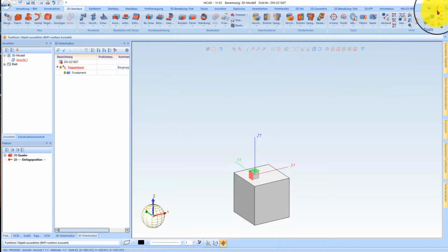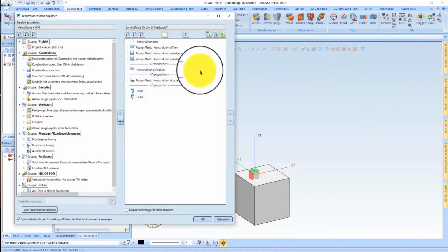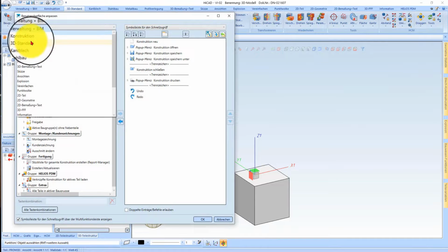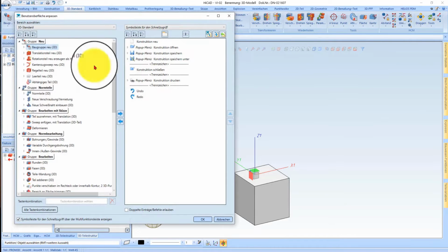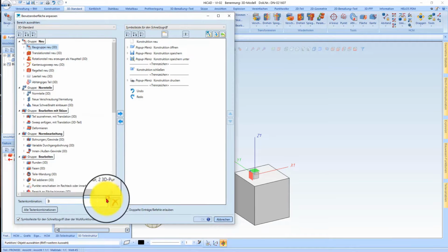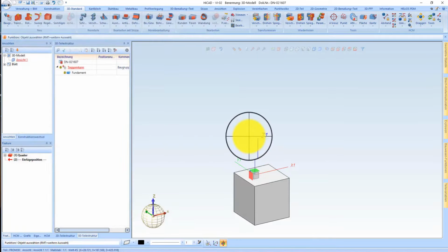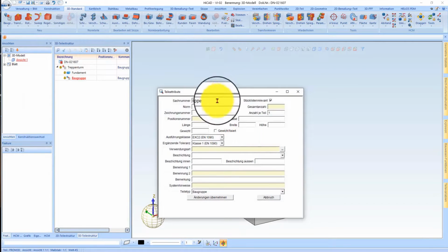What is also important, and what I always want to emphasize, is adjusting this so-called user interface. That means I can, for example, search through my commands here. For instance, I want to start a new assembly with a keyboard shortcut. That means I want to use the B key here, for example. Here it already shows me. This also cannot work for me because I have assigned the B key with a macro. For me, the B key macro is a new assembly. I would like to show that right away. That means if I simply press the B key here, I have a new assembly.